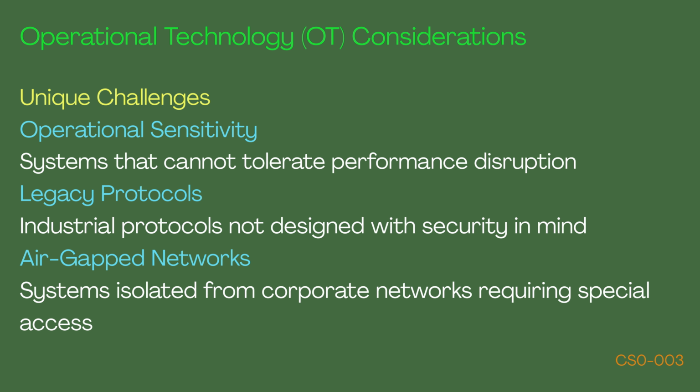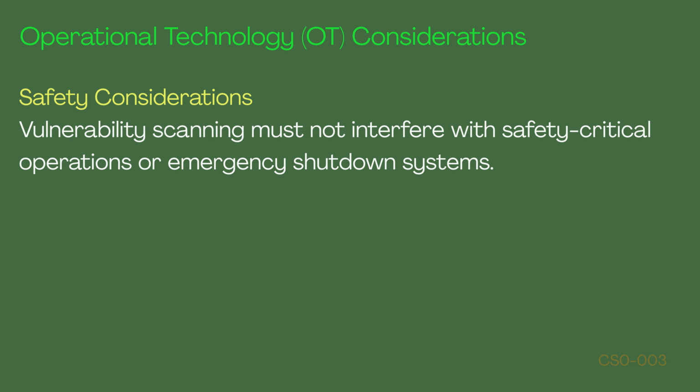And then air-gapped networks, because these are systems that are isolated from corporate networks and they require special access. They need that extra protection of being air-gapped, though because of that, they're isolated from the corporate networks, requiring special access. And you've got safety considerations. Vulnerability scanning must not interfere with safety-critical operations or emergency shutdown systems.